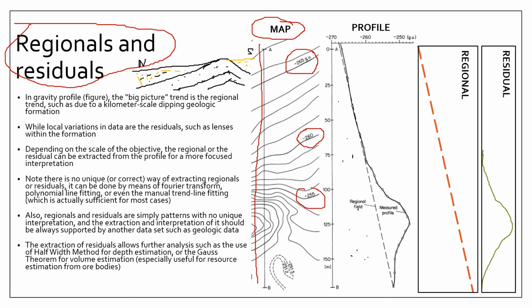Naturally, if you're doing gravitational surveys, you take a reading here. The stuff that you read here is mostly just soil, so you will get a low gravity reading, and then as you go towards the south, you're getting closer and closer to the more dense sandstone unit. So it's increasing.